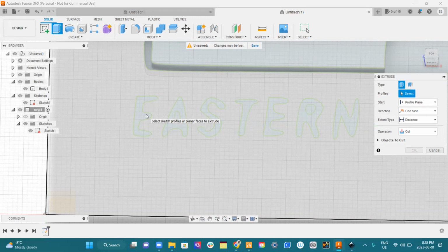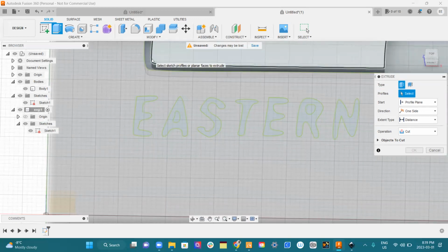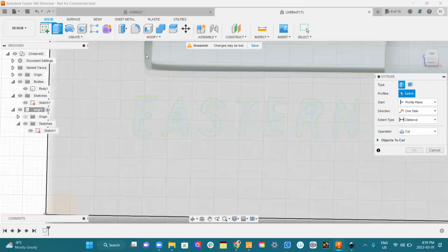Like certain things, if you select the line versus selecting the area, especially with the drill path stuff, it does bizarre stuff. So if I tell it to carve out this thing here, I could get it to carve out between the lines. I could get it to carve down to the line that's in the bottom, or I could get it to carve the flat of the bottom. Those are all different operations, and it'll try to figure out what you mean. And sometimes it does weird stuff, especially selecting the line will sometimes have it drill outside of the wood, and it'll just kind of float around drilling air.